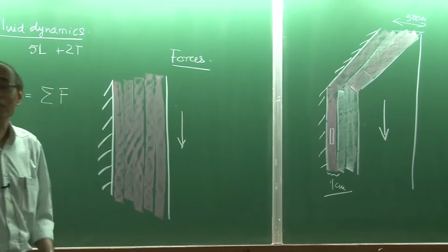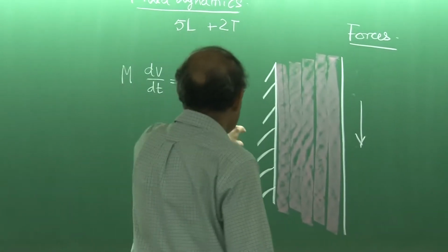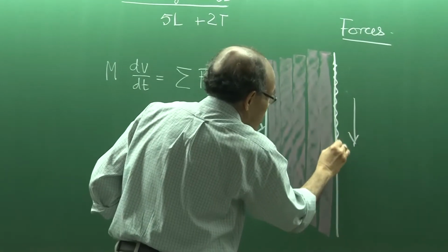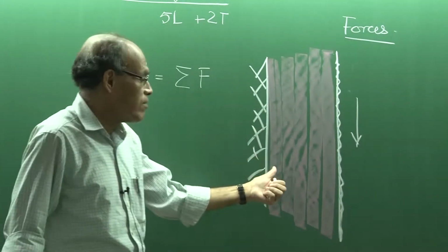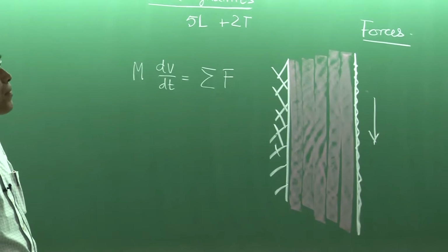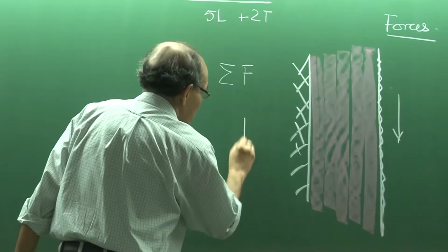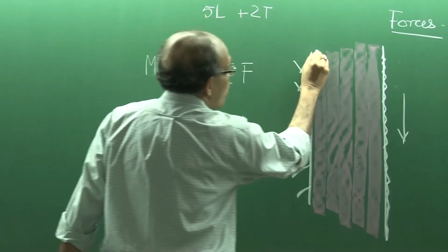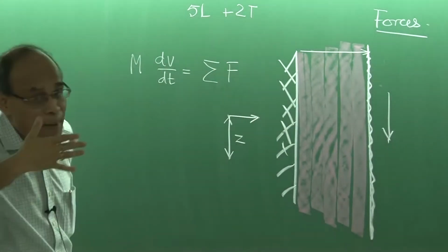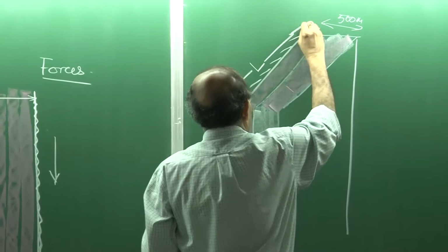Let us just treat this problem as a typical film flow problem between one moving and one stationary surface, and this represents the stationary surface. On the other hand, this represents my moving surface, and my domain of interest is in between the two. When we address any such problem, we must understand that we have to label the coordinate axis. That is extremely important for us, and let me say that this represents my z direction, the way it is shown here, and this represents my y direction. What you do not see is the depth. This part is not seen here, which is basically the width of the mold.